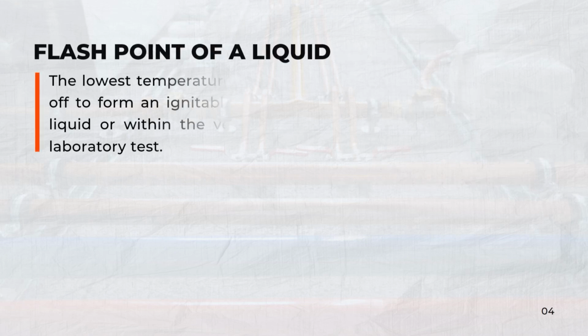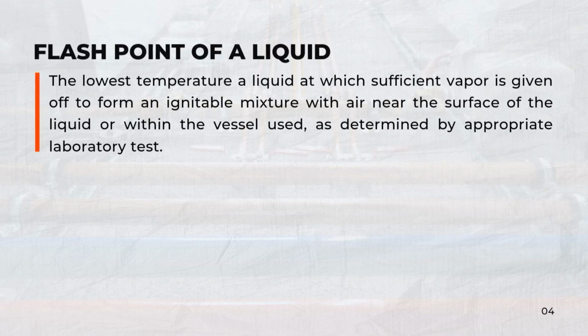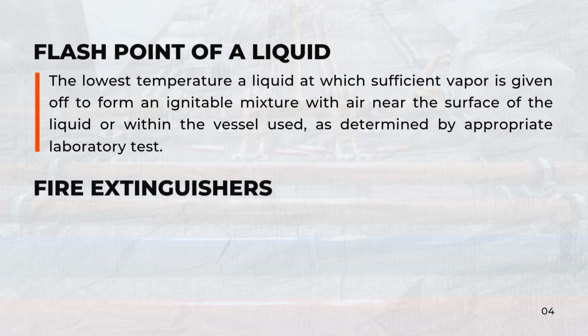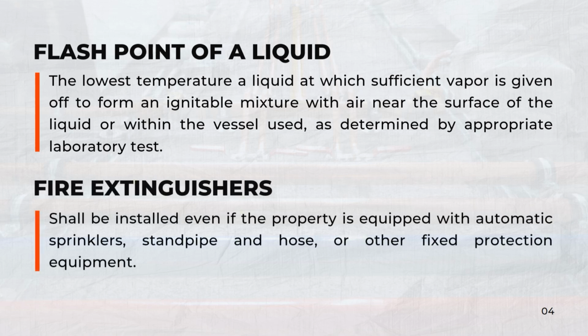Flashpoint of a liquid: the lowest temperature at which a liquid gives off sufficient vapor to form an ignitable mixture with air near the surface of the liquid or within the vessel used, as determined by appropriate laboratory test. Fire extinguishers shall be installed even if the property is equipped with automatic sprinklers, standpipe and hose, or other fixed protection equipment.